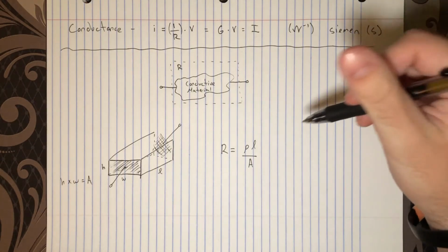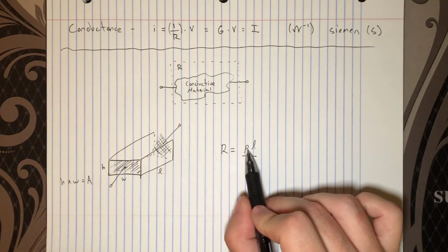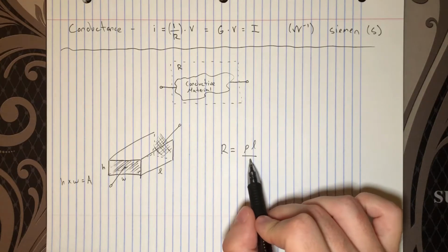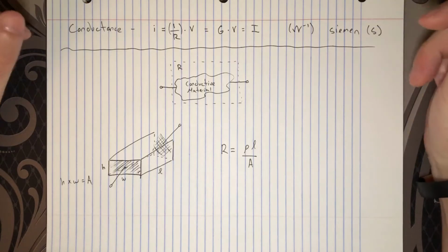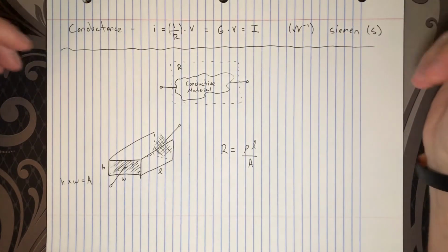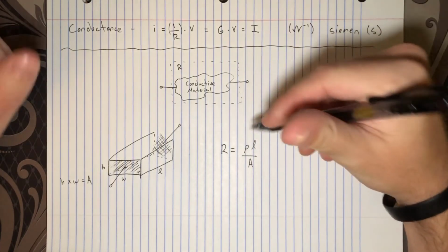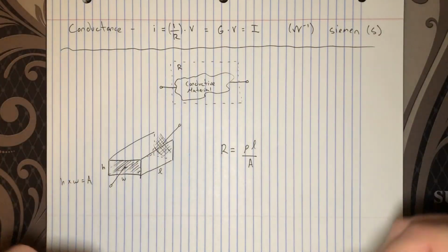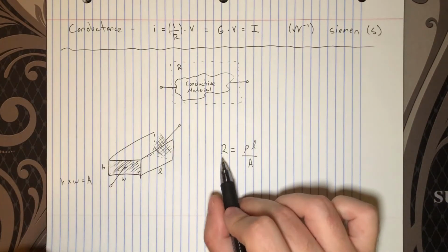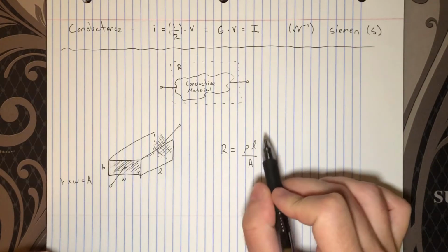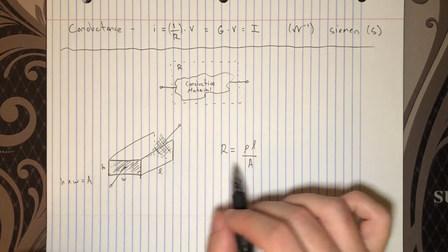And so knowing that this is how we want to define this property called resistance, which we as engineers have come up with as a tool to describe our circuit elements, well, then we can say that we can measure the resistivity by creating this rule. We can just take a metal bar of a certain length and a certain area, apply a voltage to it, measure the current through it, and that tells us that material's resistivity. So really all these definitions are backwards, where I'm saying, oh, resistance is a function of resistivity, length, and area. Really, we've defined resistance this way.